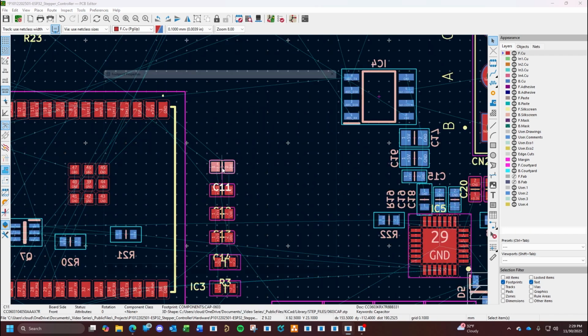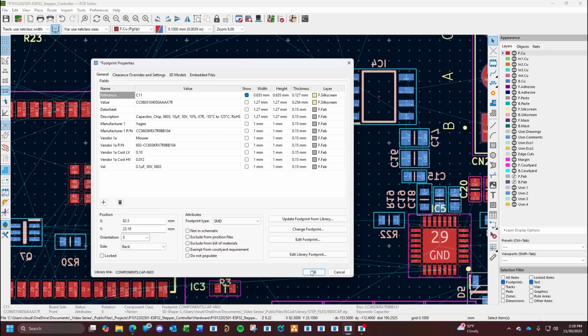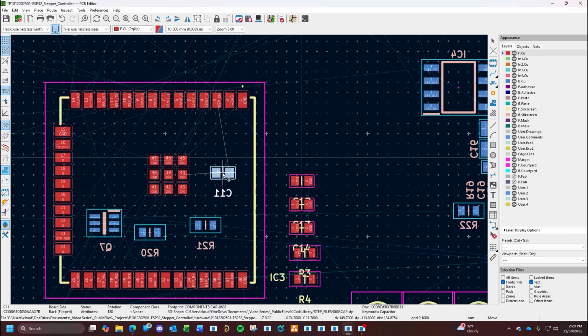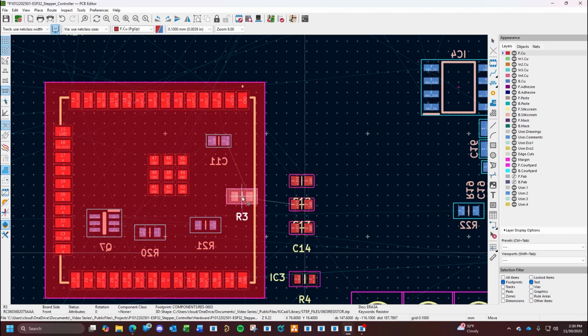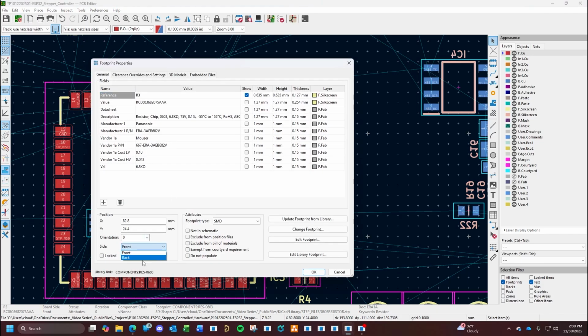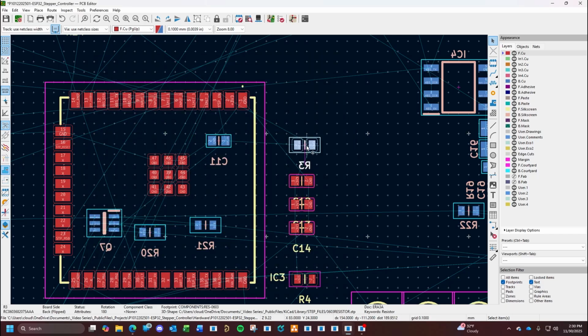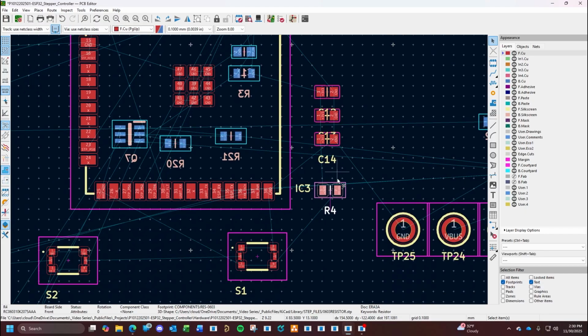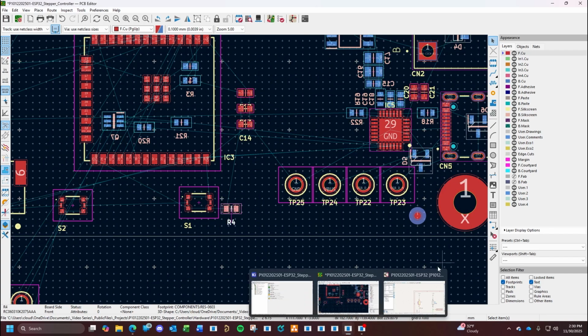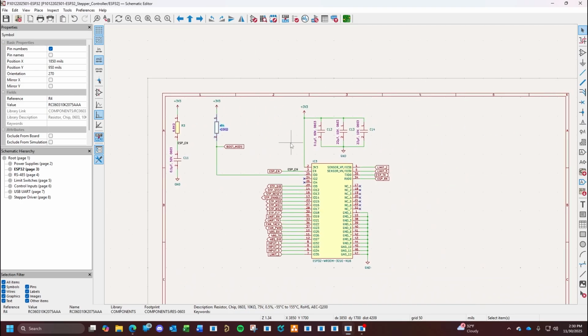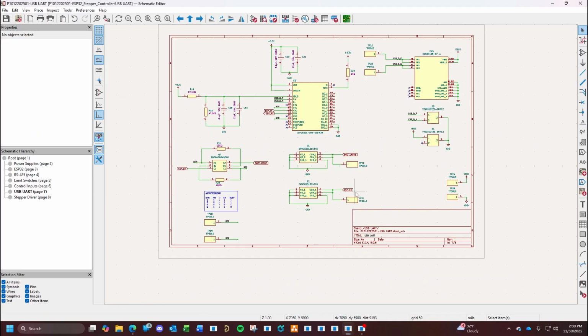Okay, so this guy we will throw on the bottom. That goes with the ESP enable. That's part of that circuit. Same with this guy. That would go with this circuit. Much easier. We'll just limit the chip. That's the boot mode. We can actually put that by that switch. And something else I want to throw in here that I've seen done on other circuits. So let's go to here.